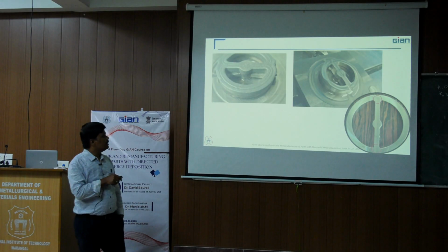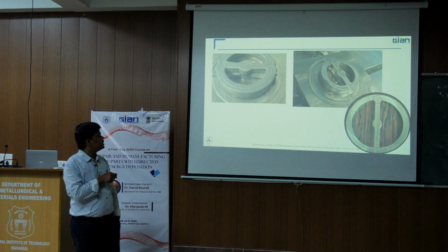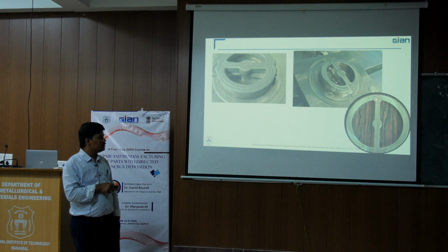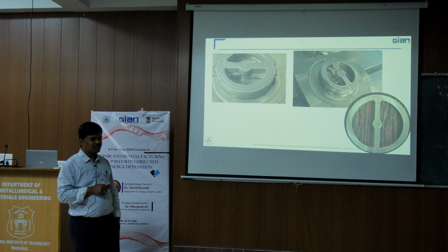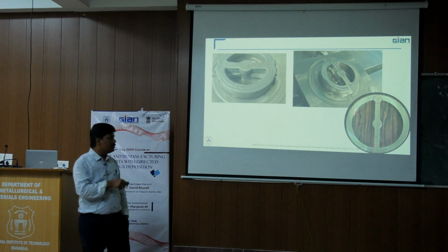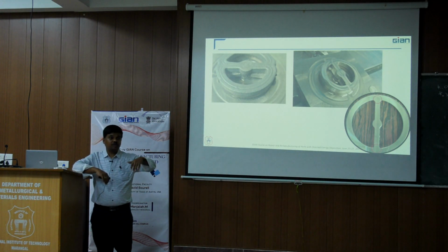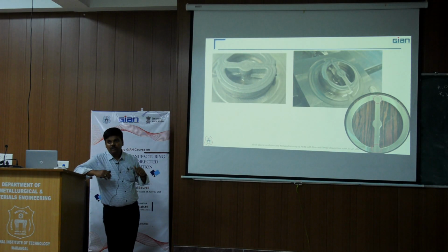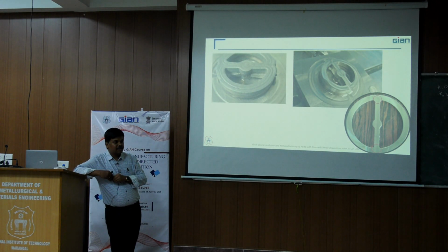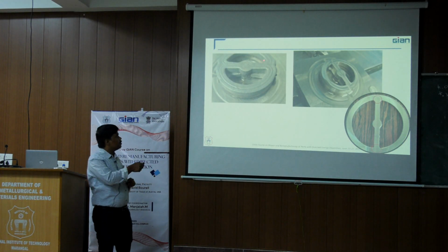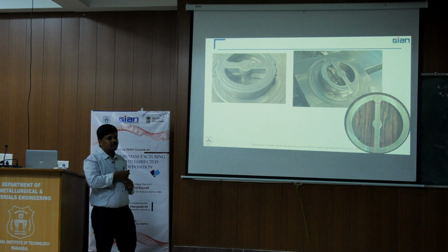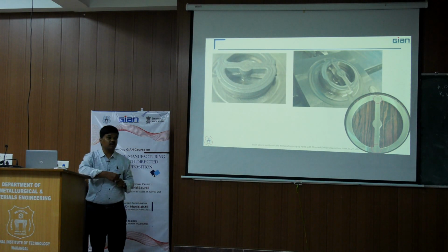But where we have the intersections at these junctions, there we have a lot of defects. This is mainly because of the interpolations of the deposition where one scan strategy interacts with another scan strategy. Definitely at these particular locations we have a lot of the defects which we have faced.